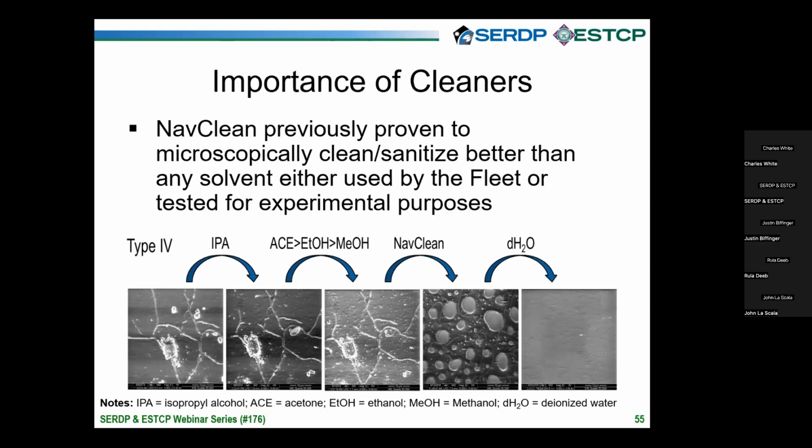Most commonly for minor outbreaks, ship's force are instructed to use organic solvent liquid cleaners or dilute bleach solutions. And these cleanings, combined with mechanical wiping, are very good at cleaning the macro growth, but are largely ineffective at cleaning the microscopic or hyphae growth and removing the spores, which cause immediate regrowth of the fungus.